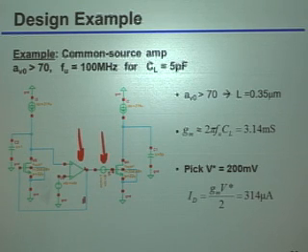But how would you do it in real life? Oh, I see. You're asking how do you do this in real life. Okay, very good question. In real life, there's probably some sort of AC coupling capacitor, or in fact, what you'll much more commonly do is, if you have a differential pair kind of amplifier, the tail current source would actually set what this quote-unquote nominal bias would be doing. It's a very good question.